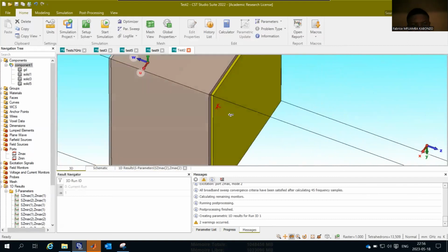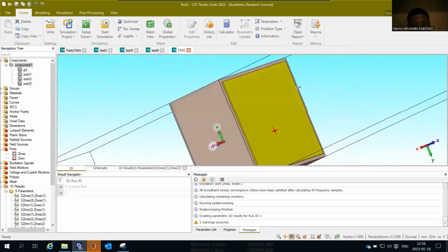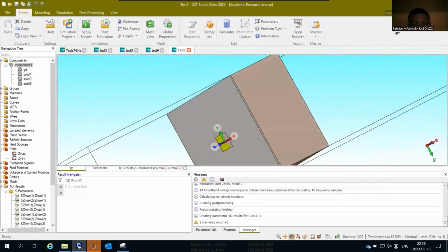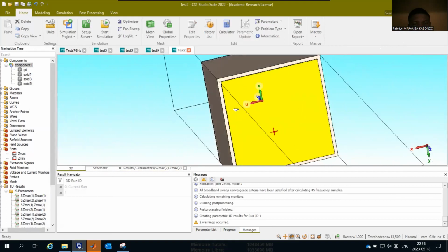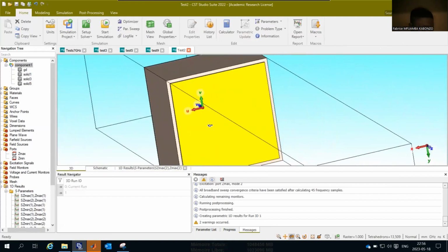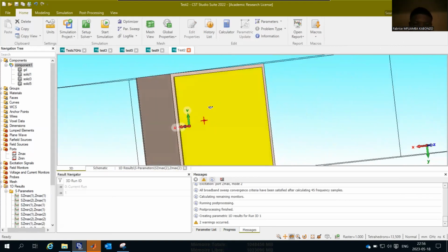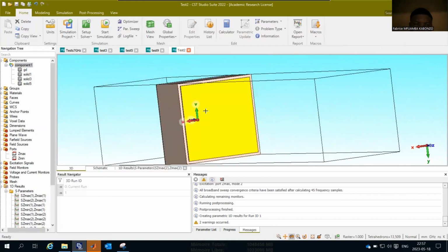You have put the same substrate size, everything is the same, right? Because we are getting the phase result exactly the same. Yes, the phase is the same. Maybe for the whole structure, you create an array of EBG structures, then place it at the bottom of the patch, then we can try once. If we get the same result, then it's fine, it's working fine.